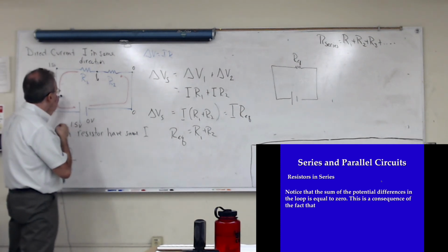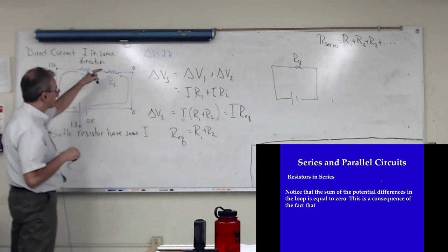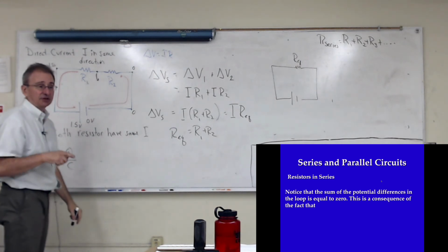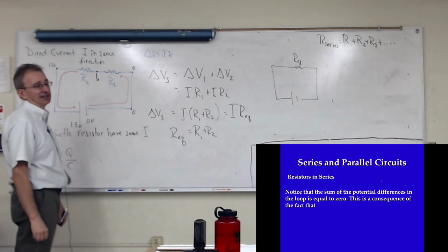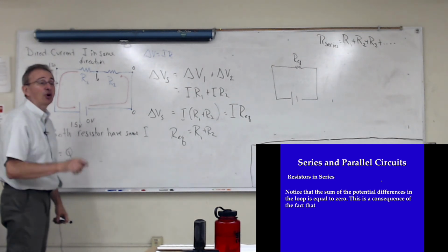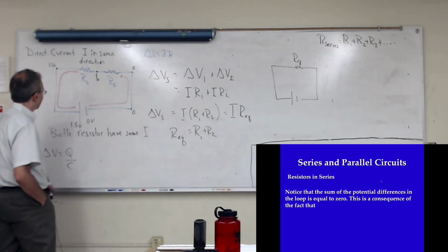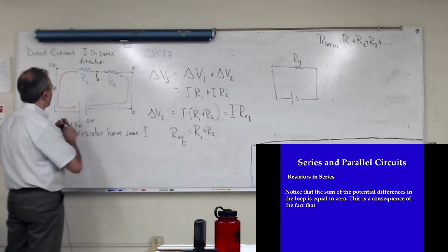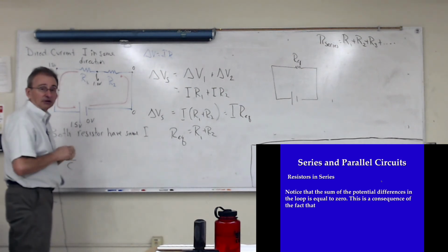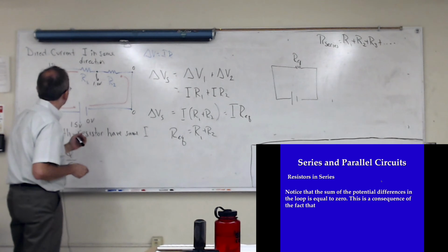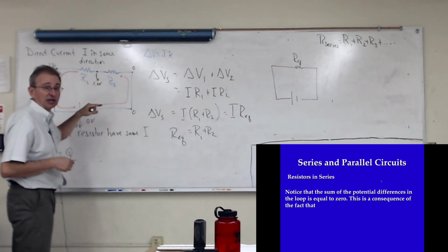If I sum the voltage drops all the way around the loop, I get 0. Because this goes to your question, Scott, you asked earlier. It's going to be important when we analyze more complex circuits. Let's say this is 1.5 volts. Let's, for fun, just call this 1 volt, just for numerical sake. I'm going to go around clockwise and just add up all the delta V's.